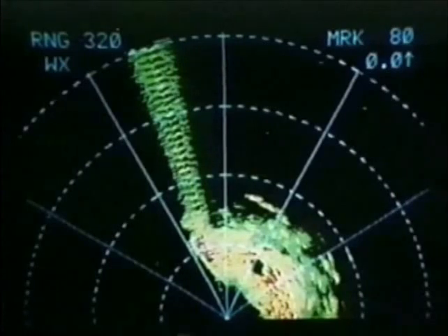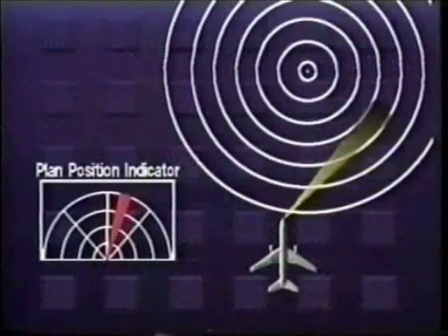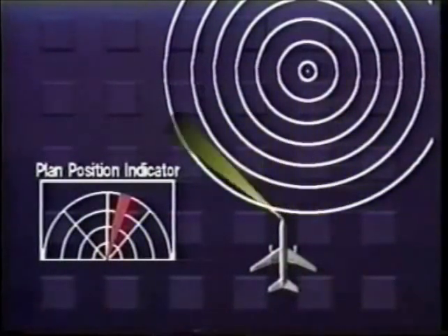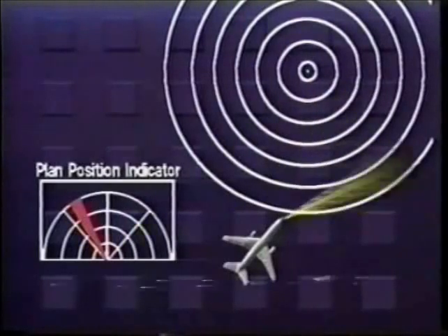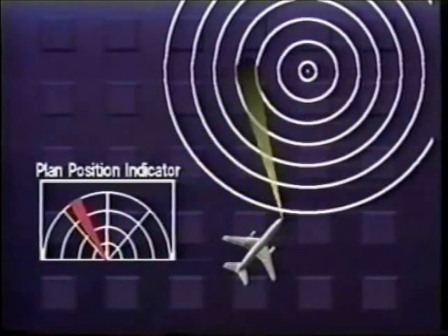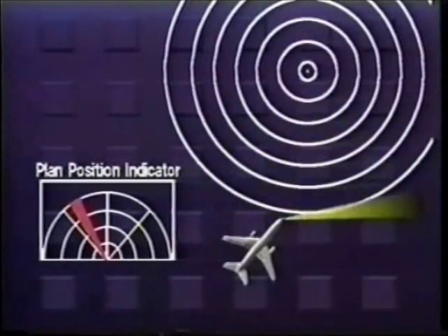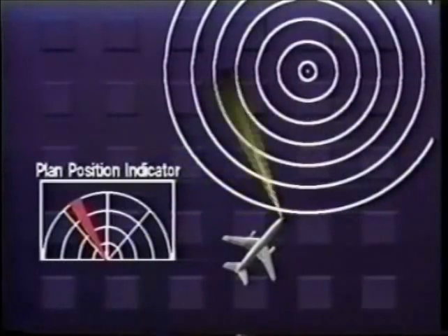The weather radar industry uses the term spokes to represent any presentation on the radar display unit which resembles wagon wheel spokes. The main cause of spokes is usually interference from powerful military ground radar. This does not indicate a radar system failure. If you are uncertain whether the radar system is malfunctioning or if the spoke is being caused by an external source, change the heading of the aircraft slightly and notice if the heading of the spoke changes in the opposite direction the same number of degrees. If it does, it's external interference. Ignore it.